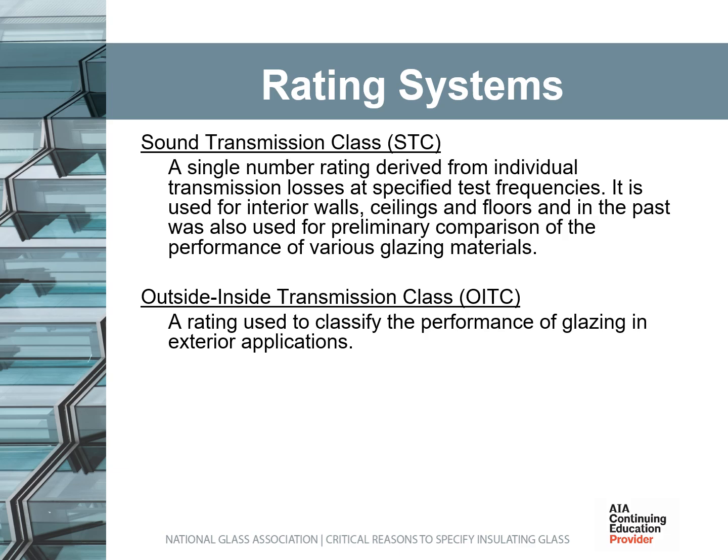STC and OITC are completely different rating systems that result in different values and cannot be compared to each other. STC was originally developed for rating the acoustical performance of interior partitions, as at the time there was no method for rating the acoustical performance of building envelope components. STC was used for this too. Unfortunately, it took quite a few years for the OITC system to be developed, and by the time it was introduced, STC was used throughout the building component industry, even though it was not intended for this purpose. That's why STC is so frequently referenced for windows, doors, etc. OITC is gaining slow acceptance as a replacement.